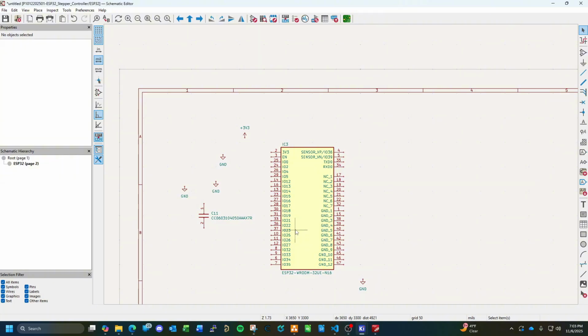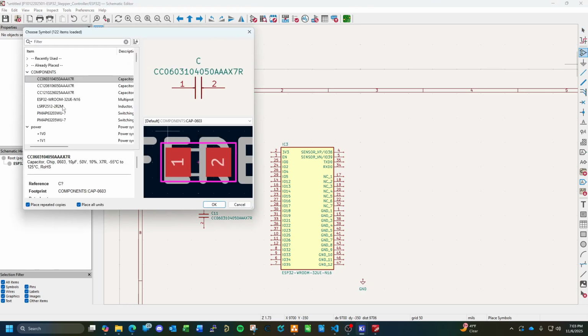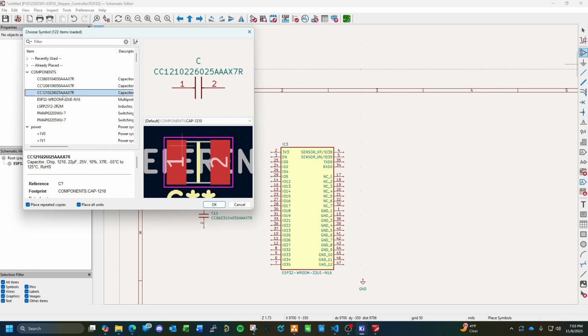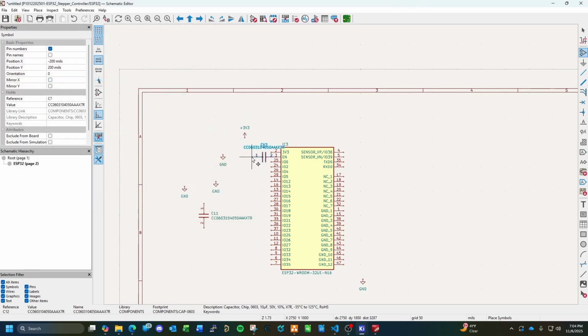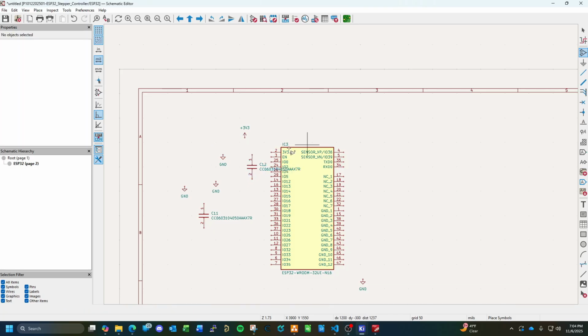And usually with switching power supplies, they go pretty quick. We're also kind of, let's see here, 12, 6. Those are some heavy duty caps. Those are 25 volts. We'll see if we can find some 22 microfarad at around 6 volts, to use for some bulk capacitance on the input side of this. We're also going to throw in another 104 cap to help filter noise off the 3V3 line. We'll get all this cleaned up.